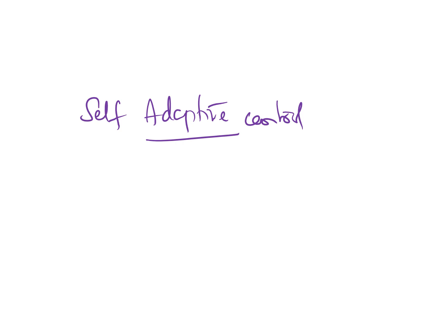If the process is not known well, already we know the system identification: we know the input, we know the output. If the process is not known to you, we need to evaluate an objective function using the controlled output values. Then the adaptive mechanism will change the control parameters in such a way as to optimize the maximum value of the objective function. So I will explain with an example.